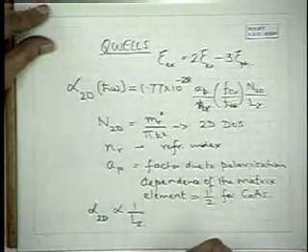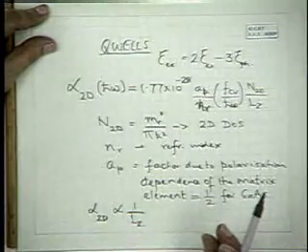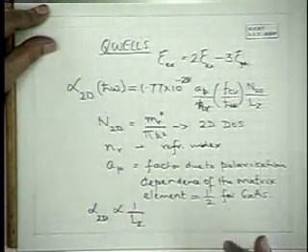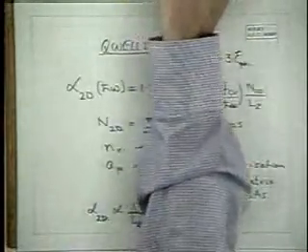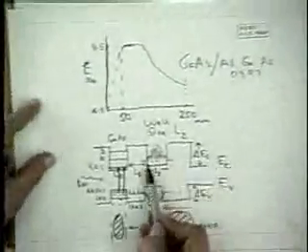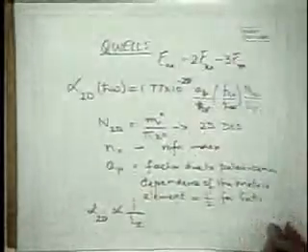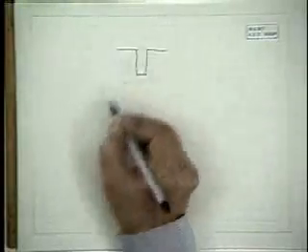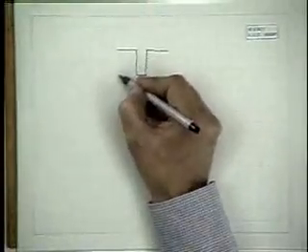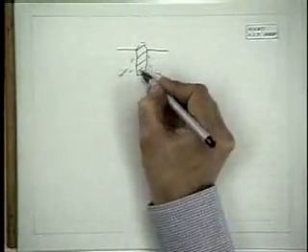There is an optimum value of Lz, because as Lz becomes smaller and smaller, the electron wave functions cannot be confined within that potential well. It spreads out, it decays into the barrier. If you make this extremely small, then the wave function tunnels into the potential barrier. For example, if you have a very narrow potential well, then the electron wave function will go like that, and only a small portion is within the well.